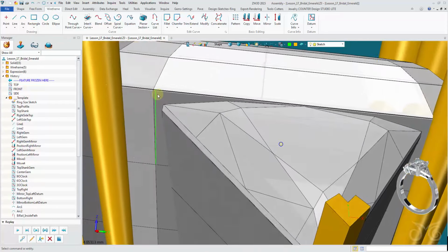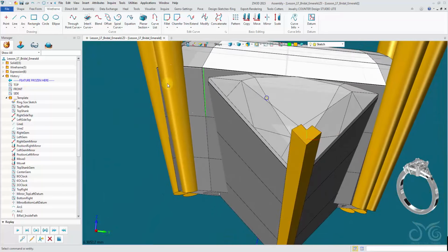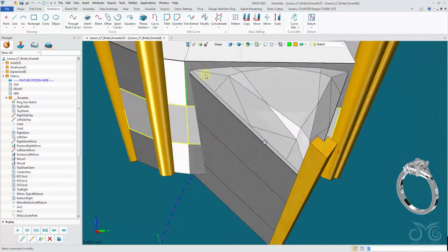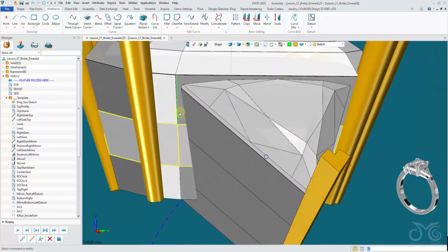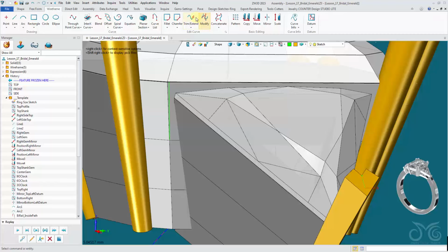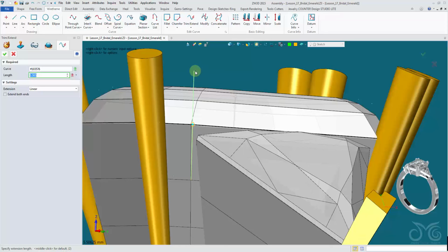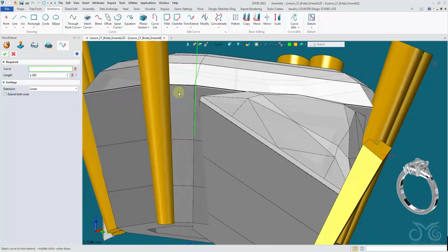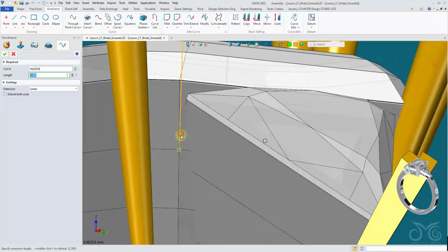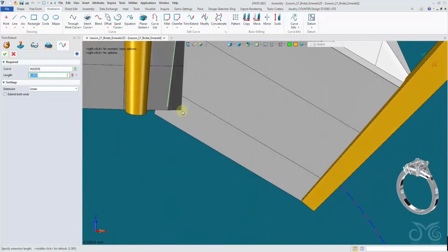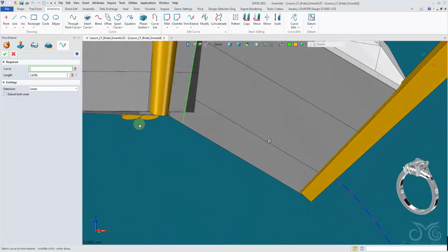Okay, here is a line that has the orientation of that prong. We'll be using this to create the curve with which we sweep along. So let's trim extend it. Extend it up 2 mm, oh, just 1.5 millimeters is fine, that end. And the other end, let's bring it just below into the ring finger.